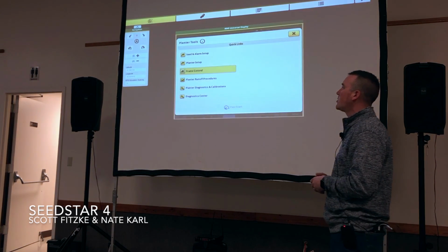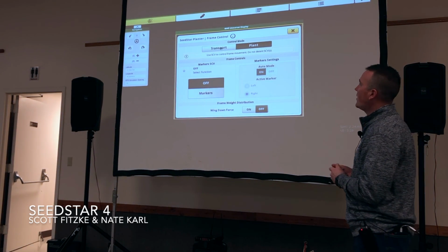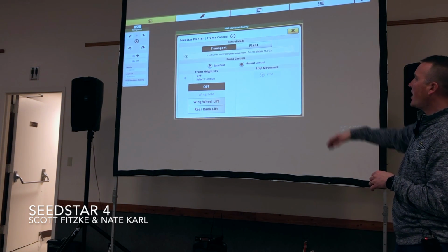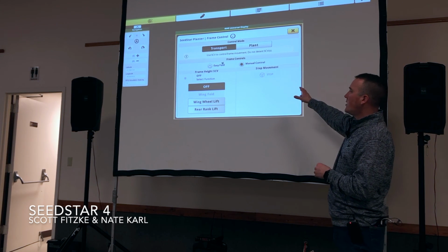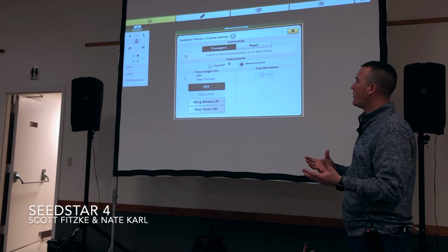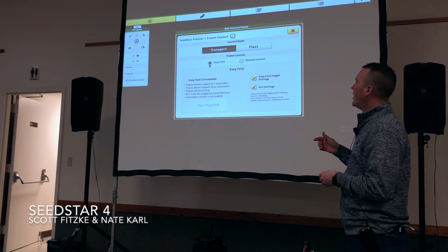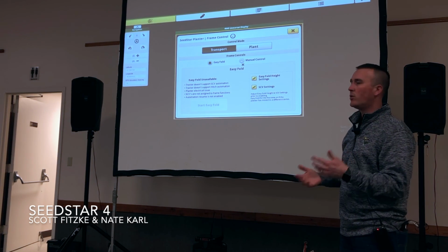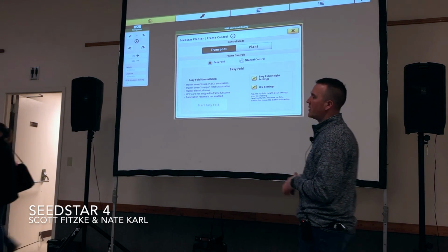We jump into frame control. So we've got a few different options here. We've got our manual control mode to fold and unfold the planter. And we also have Easy Fold. So with the automation functions on a planter, we do have Easy Fold that we'll basically set up the first time, tell it what SCVs we have assigned with what functions on the planter, and then it's going to do the folding essentially for us.